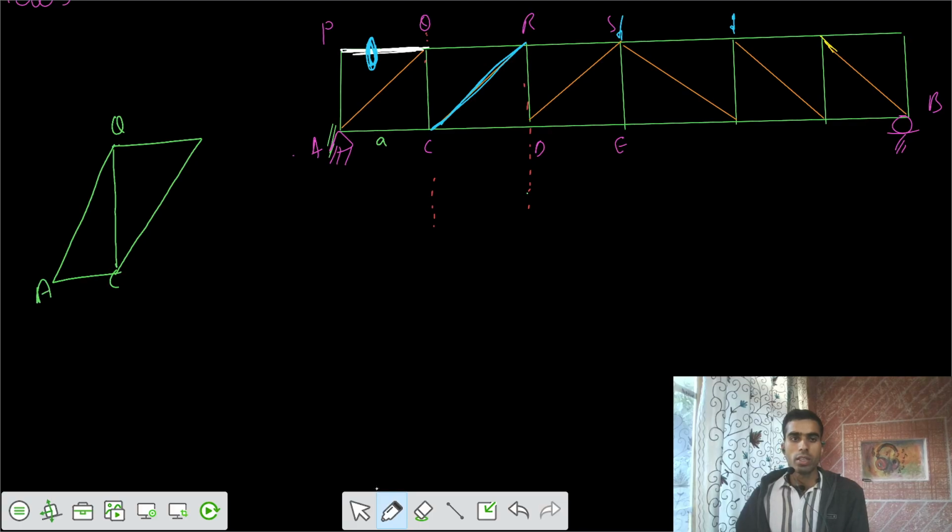Now what is the condition we can have? You can't directly say for the QC, it's a function of joint, it's a function of loading, on what joint you are applying the loading. If I talk about deck type loading, that means critical joints would be these two. Then if I talk about through type loading, the joints critical are these two. So this is the difference. So we have to see where the loading is applied.